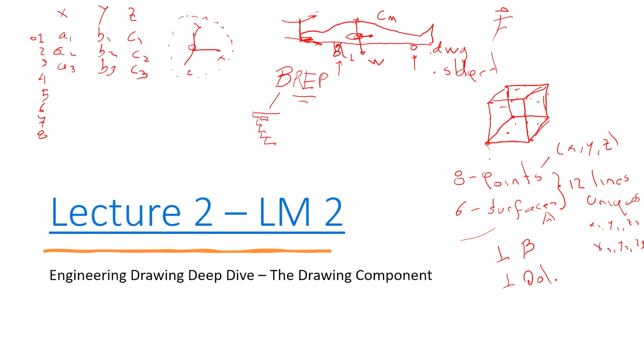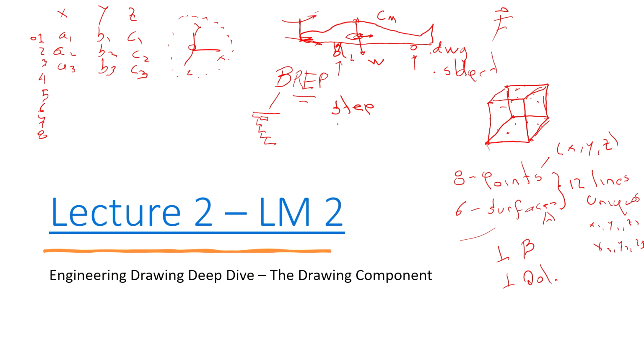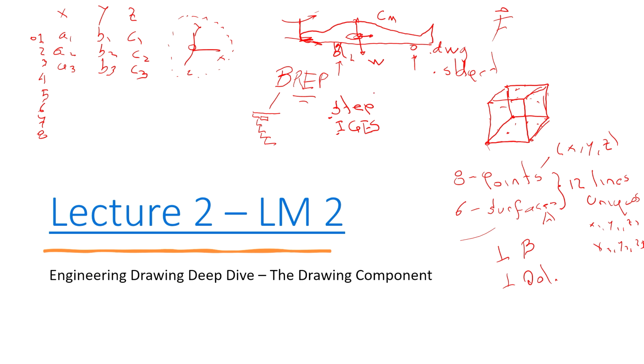Once you have your points, your surfaces are created within the CAD, and the lines are traced, and the body is created. The files to export this are usually STEP, which I forget what it stands for, or it could be IGES. All these things mean something, but right now it's not as important what they mean as to know that these are standard formats for exporting parts. Okay, you can have Parasolid, and this is if it's bodies, right? Solids.